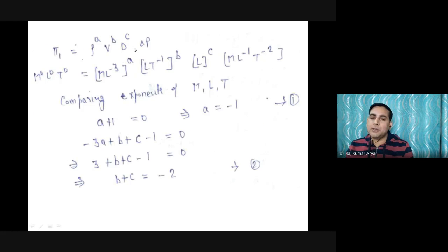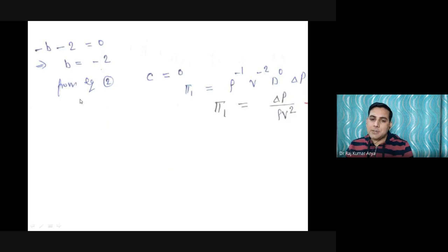Here first we want to calculate the pi group. So first we involve them with your delta P. Calculate the same way by dimensional balance, calculating coefficients a, b and c. So you got your a, b, c here. For that you also got a constant, and finally you got a number, delta P by rho V square. What is this number called? I taught you: if you put a coefficient half here, it's called your pressure coefficient. Correct or not? If I put a half here, this is called the pressure coefficient. So this is the first dimensionless group.